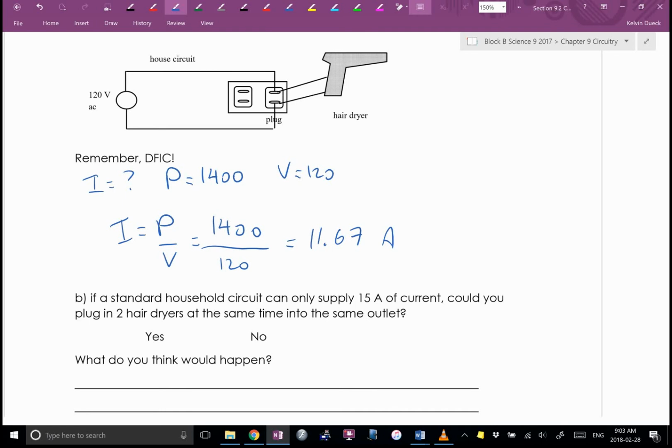Many of you may have tripped a breaker and then been, I don't use this word very often, dumb enough to try and replug the same device in and been shocked. Why did the breaker go again? Because you're still asking that whatever you're trying to plug in is requiring a total of more than 15 amps, because there's something else that's drawing current as well. It's also why you may notice the plug was just fine running the blender, but when I turned on the microwave, that's what blew the breaker, because now adding both of those currents up was more than 15 amps. Does that make sense?